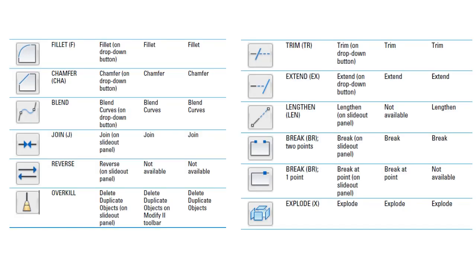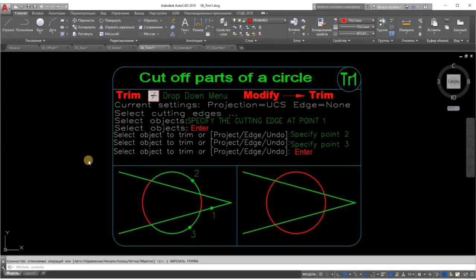The commands in the next section, Trim, Extend, Break, Fillet, Chamfer, Blend and Join, are useful for shortening and lengthening objects, for breaking them in two, and for putting them back together again. Trim and Extend. Trim and Extend are the twin commands for making lines, polylines, and arcs shorter and longer. The two commands and their prompts are almost identical, so the following steps cover both. We show the prompts for the Trim command. The Extend prompts are similar.